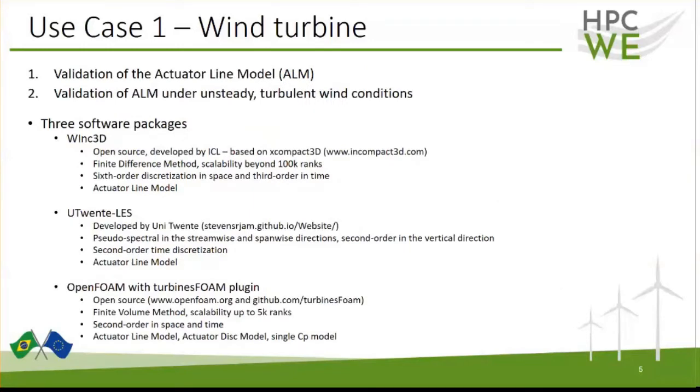Then today I will show you 2 works that we are developing. The first one is the validation of the actuator line model itself. And a second study is the validation of this actuator line model under unsteady turbulent wind conditions. I will show results using 3 different software packages.